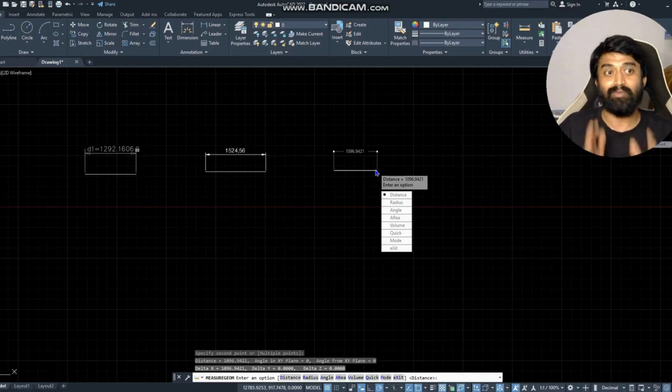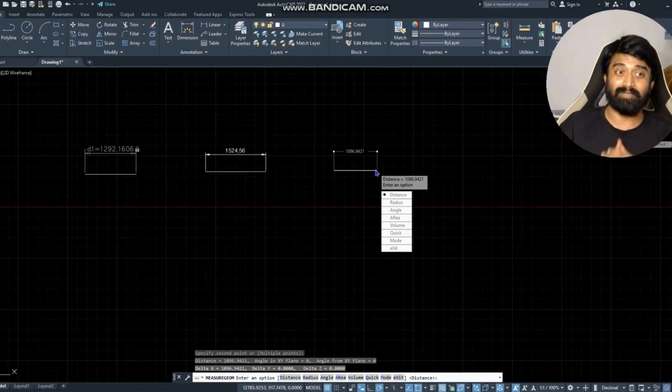Then the client can easily make trouble for you. So at that time, while you are submitting the project, you have to carefully apply non-changeable dimensions. Why am I telling this? If you apply non-changeable dimensions and the client changes them to make trouble for you, the original object dimensions will not change. Only the digits will change. In such conditions, you are in the safe zone, whoever tries to make trouble for you. Their values will change, but the dimension size will not change. So at the last date of project submission, like the 15th or 13th, we will remove the changeable dimensions and keep non-changeable dimensions.